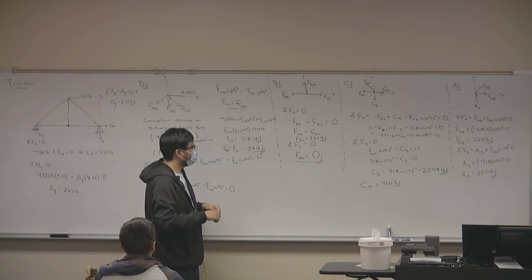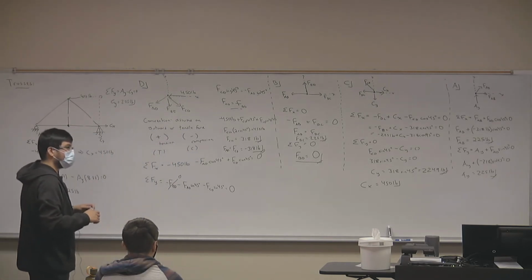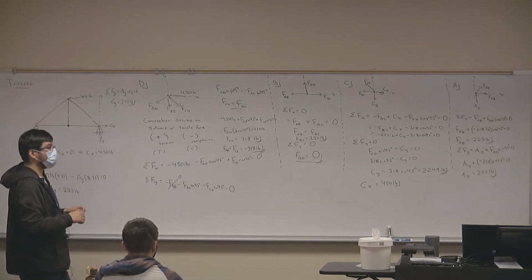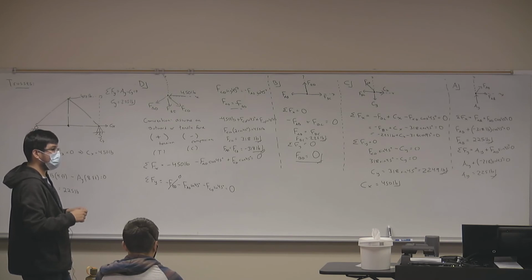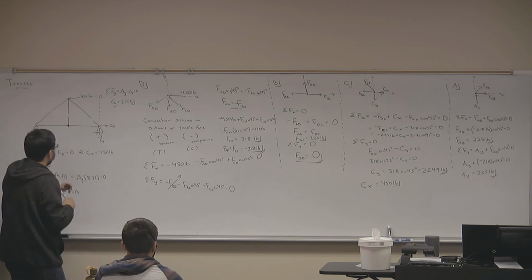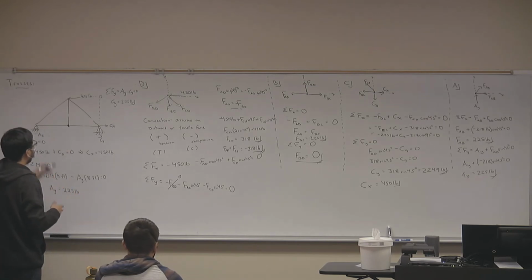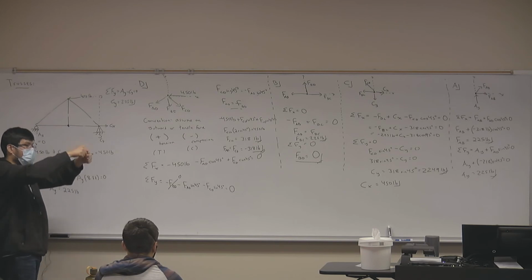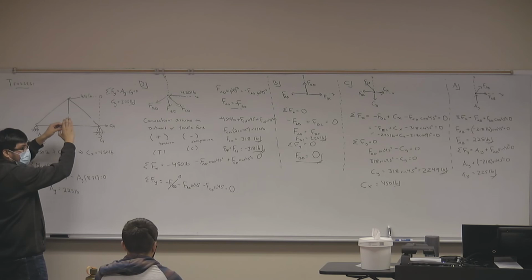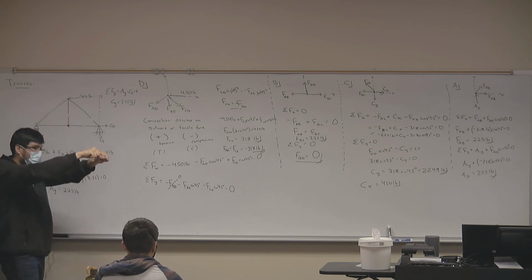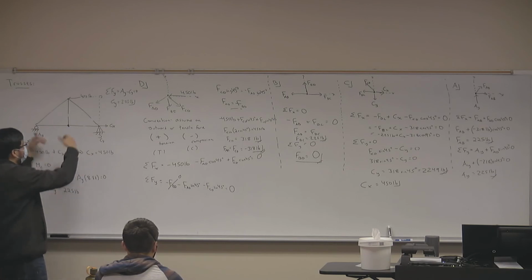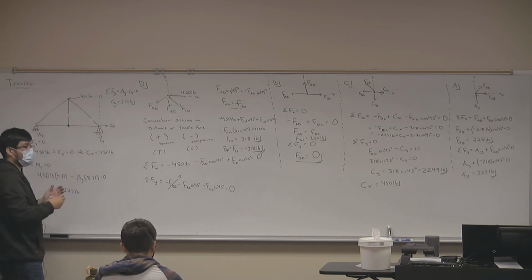Okay. So we were saying at the beginning, because there's no translational motion, that's the reason why only tension or compression could act on it. Not just because there's no translational motion, but because these are rigid bodies, there's no shear motion, which means this is a rigid body, its shape cannot change. Because its shape cannot change, you cannot bend it. If you cannot bend it, there's no shear force, there's only normal force. So only tension or compression. That's just part of the definition of a rigid body.